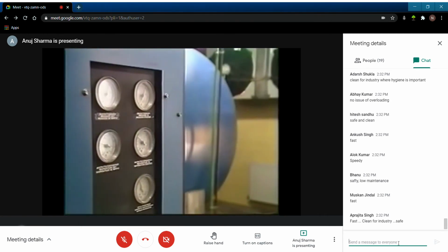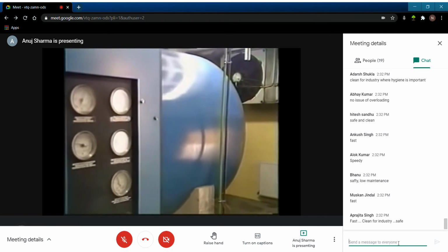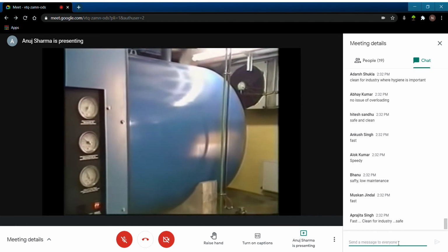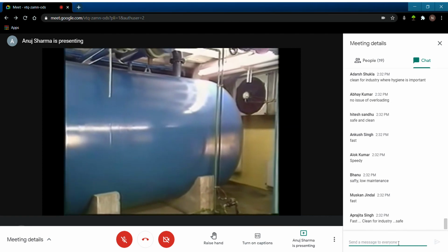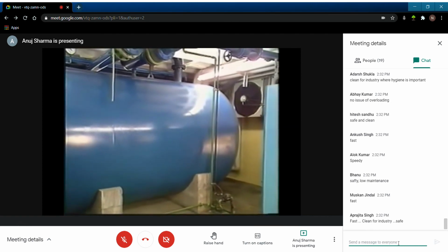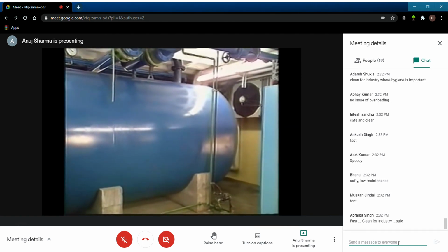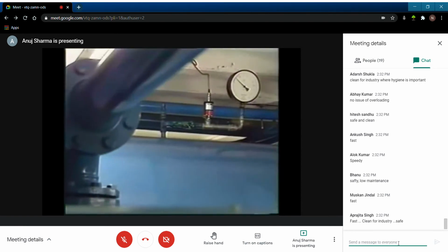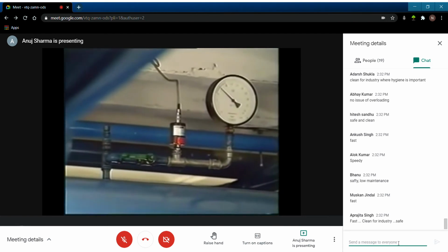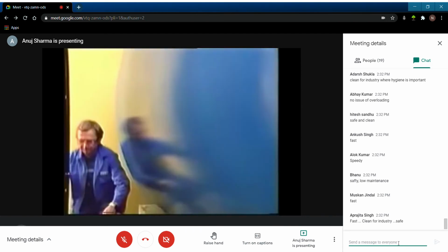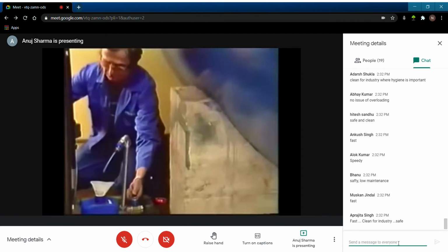The compressed and cooled air is then stored in a tank called a reservoir, which performs several functions. It acts as a buffer, smoothing pressure fluctuations as the air is used by the circuit. This also allows the compressor to run only when needed to pressurize the reservoir. The reservoir also supplies a steady flow of air to control circuits. This reduces fluctuations in pressure under varying rates of use.